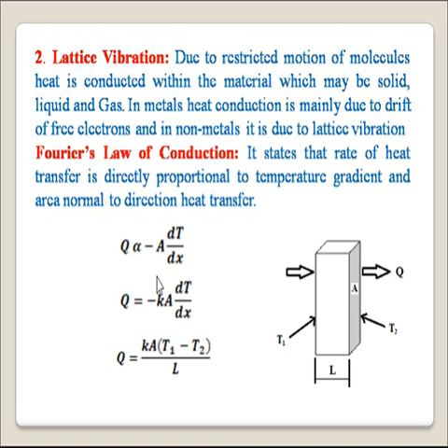Heat is conducted through the material, and this mode of conduction is more dominant in non-metals. In metals, mainly heat conduction takes place by drift of free electrons, and in non-metals, mainly heat transfer takes place by lattice vibration.